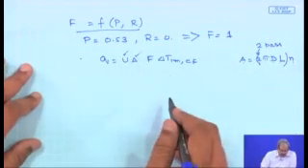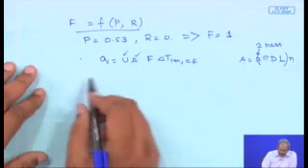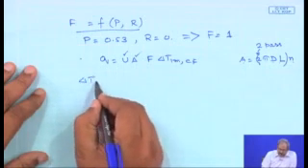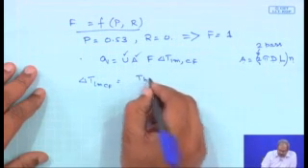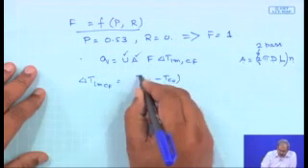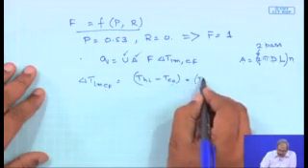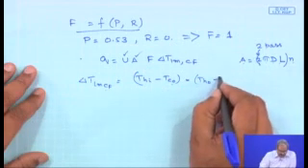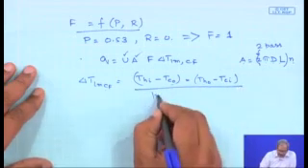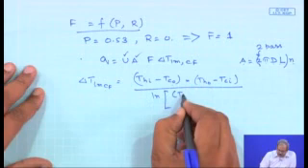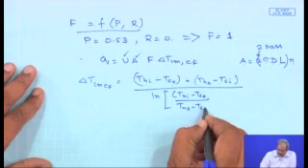The value of U is known. So, the only unknown that we have in here is delta T log mean counter flow, which is T H I minus T C O. This is based on counter flow, that is why I have O over here, minus T H O minus T C I, divided by ln of T H I minus T C O by T H O minus T C I.